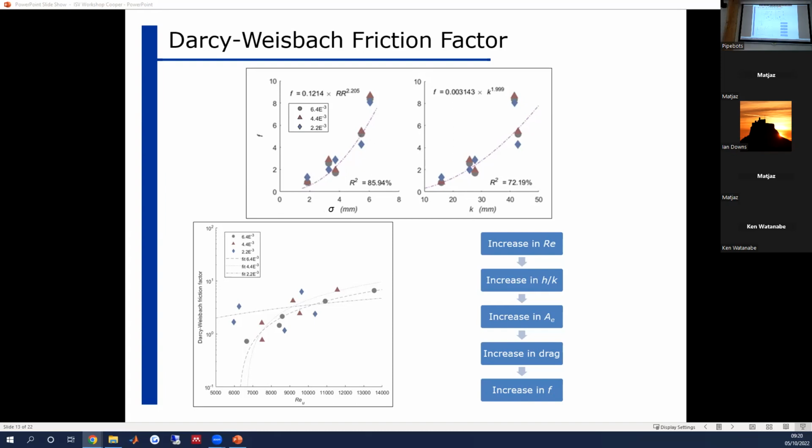So in other words, flow resistance is going to reduce with an increase in the Reynolds number because you're getting that increase in relative submergence. Whereas in overland flows, because your submergence is less than 1, as you increase that Reynolds number, the projected area of those roughness elements exposed to the flow will increase. And that accounts for that upward trend for these low submergences.